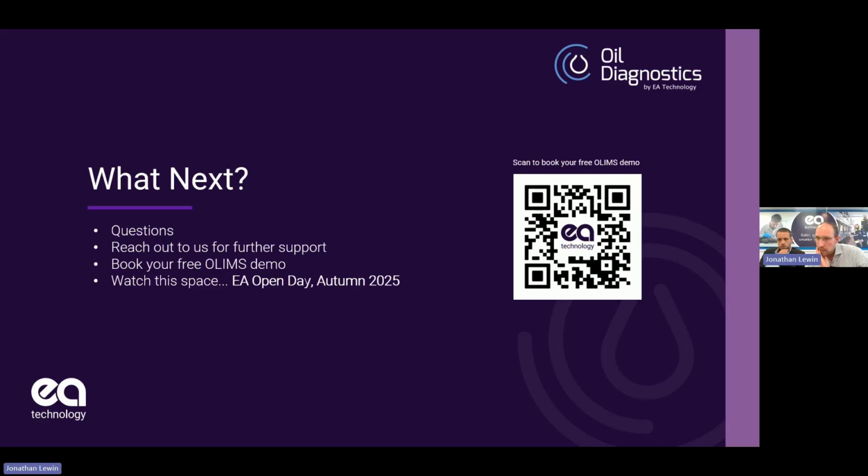So another one from Hamit. There is a new oil, FR3, which is a biodegradable oil and marketed as having better physical properties than other oils. Do you have much experience with this oil, and how do these parameters indicate as our fault changes? Manufacturers will always say that their fluid is better than another one. FR3 is one that is used. We do FR3 testing. The problem you have with the newer fluids is that because they are new, you don't have the same level of data.